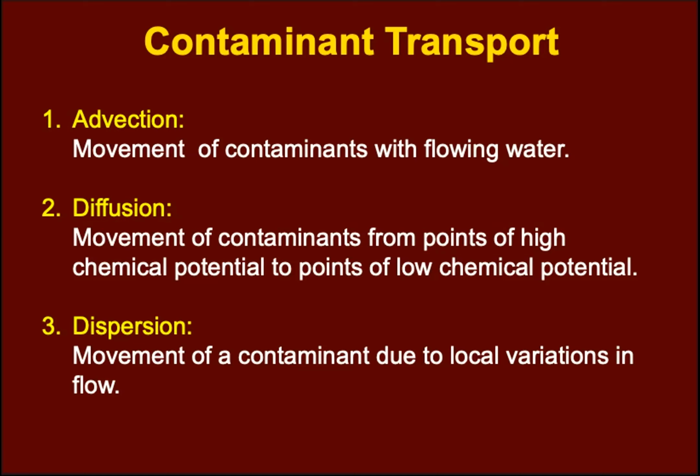Depending on the critical chemical or contaminant that we are looking at, we should make sure that the degree of contamination and the concentration of the chemical that is detected in the groundwater or aquifer at any time throughout the contamination lifespan of this landfill is always less than the maximum allowable water concentrations of this contaminant that are typically set by the Ministry of Environment of the country that you are in.